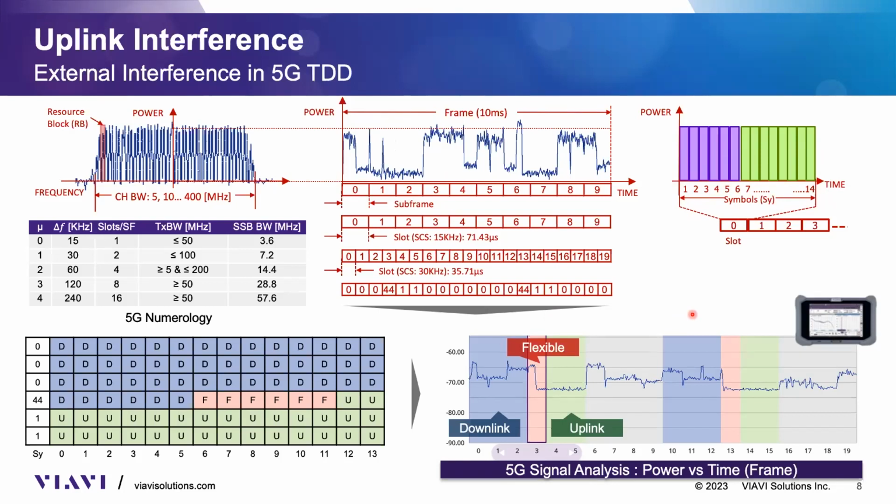Okay, before I continue, let me stop for a second. It's probably a little too much information, but I really wanted to explain how 5G TDD is a little bit more complex. At the same time, we have some opportunity here if we can tune our analysis into the flexible slots in an easy way. We can find external interferences very, very easily. So let me pause and see if there are any questions.